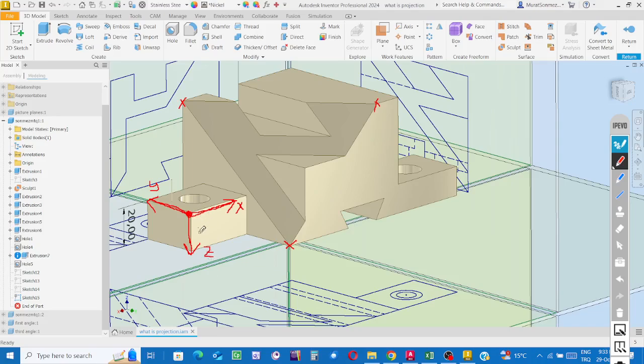Then, using such a coordinate system and starting the polyline creation process in 3D, we can draw the boundaries of the oblique surface, and then indicate the area, a region bounded by these boundaries. Apply the extrusion process. After creating a triangular prism, by subtracting it from the rest of the body we can create an oblique surface. That is what to do in AutoCAD.